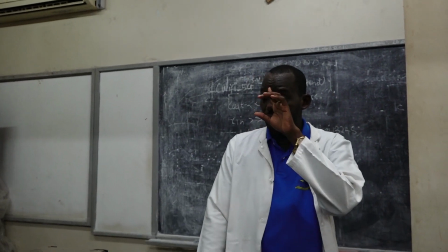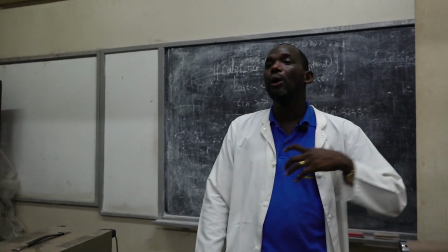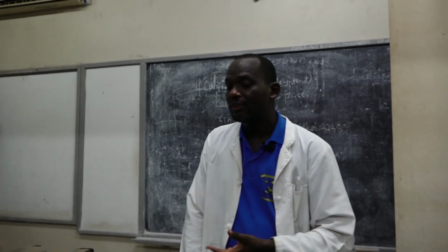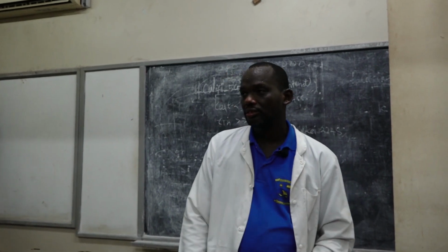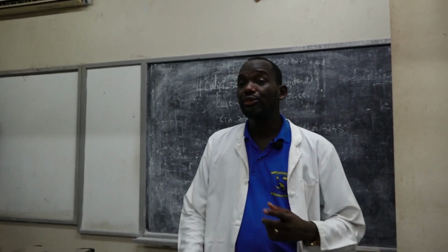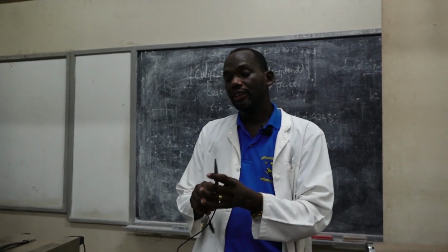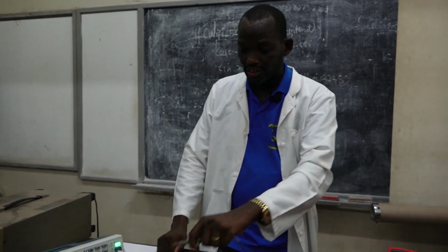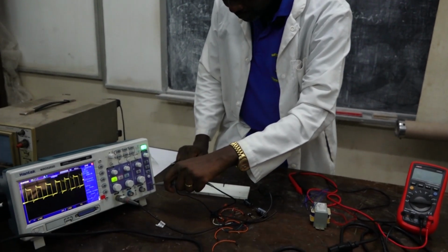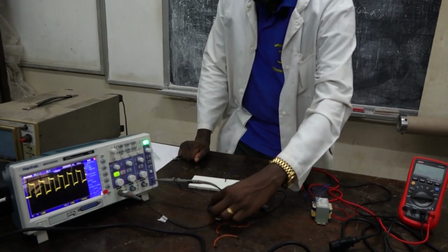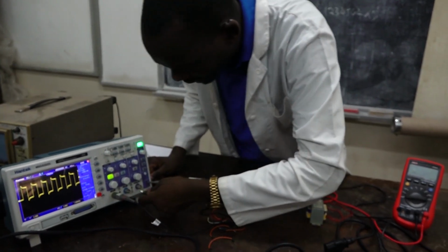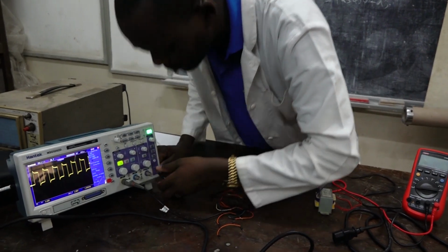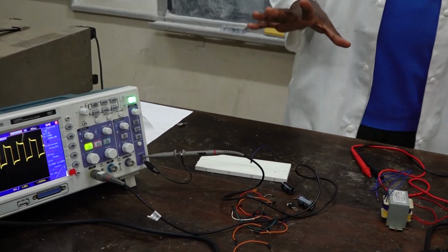So this is the actual setup. We are setting our digital oscilloscope before you feed your input signal, when you want to study the waveform in that signal and do the measurement. Are we together? So now I'm going to connect the BNC in order to do the default setting. I just press in this way and then connect it here. Then I connected this ground probe into the ground terminal. So now I have finished the connections.